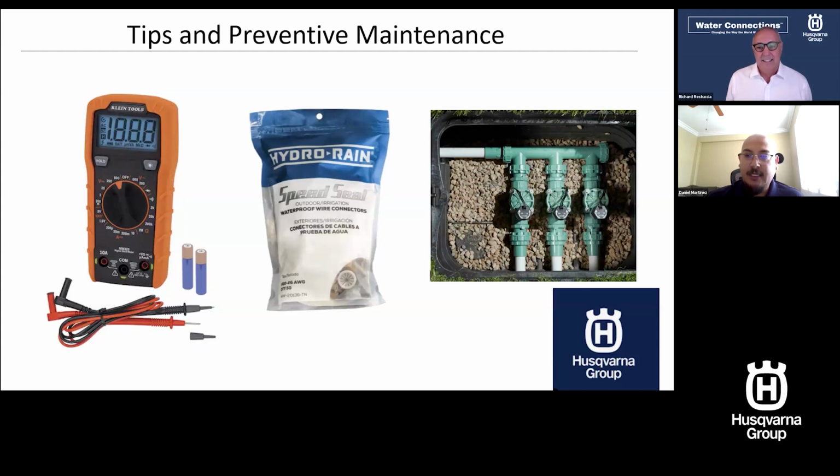Replace the old damaged one, tighten those back up, and you're back up and running. No waiting for PVC cement to set up. Yeah, I can't imagine how much time that saved you. That's fantastic. Especially if you have a high pressure system, or you're in a cold weather area, sometimes you might need to shut the water off for 24 hours or more to allow that cement to cure properly. Yeah. Very nice.